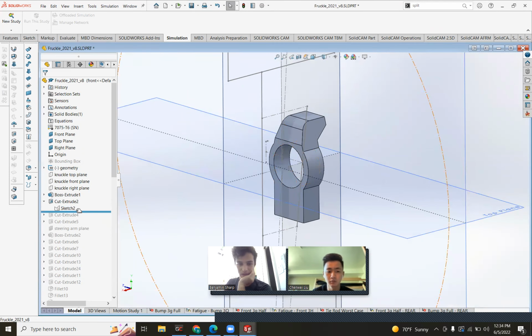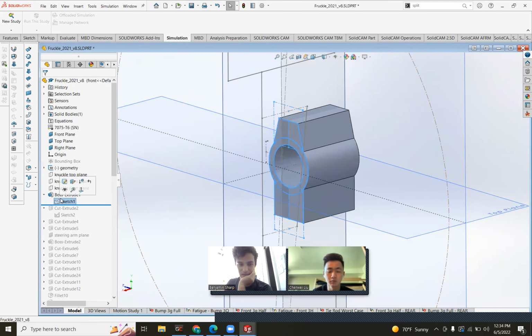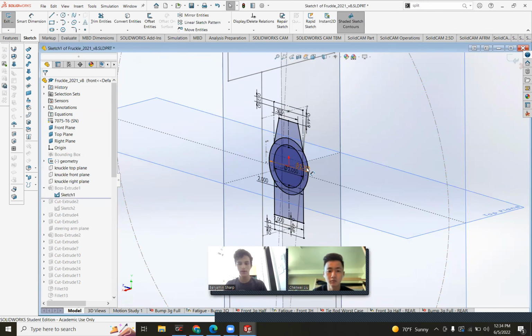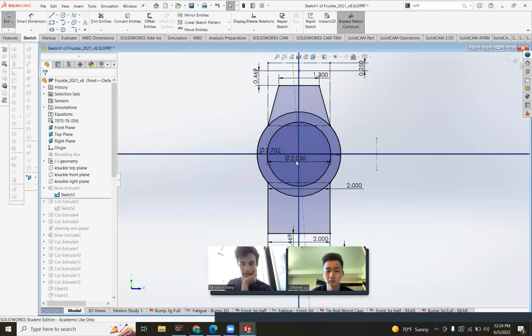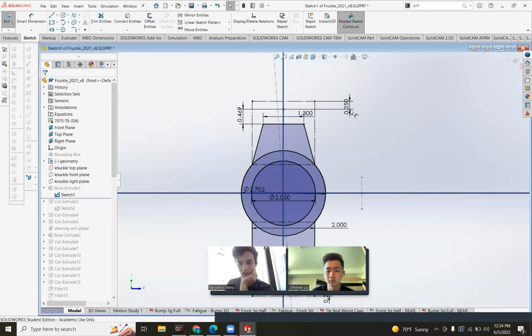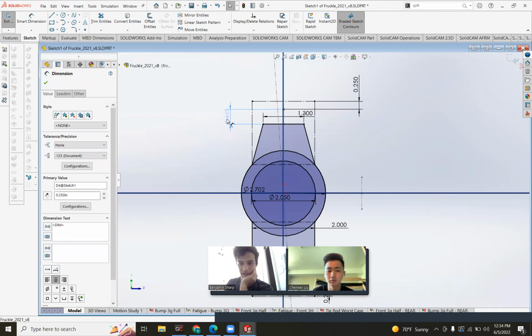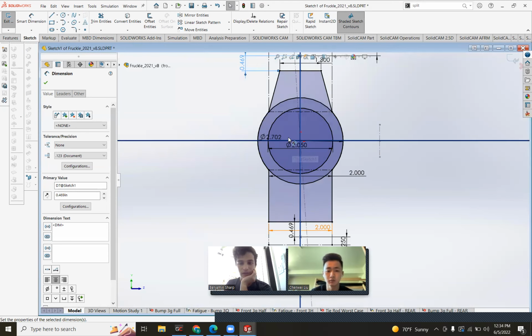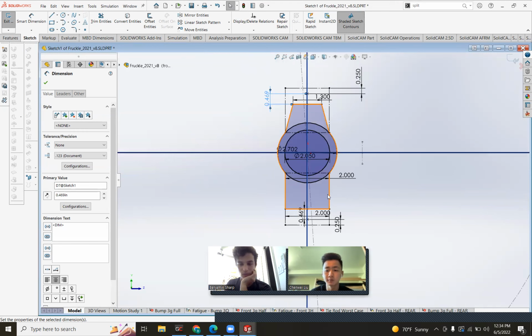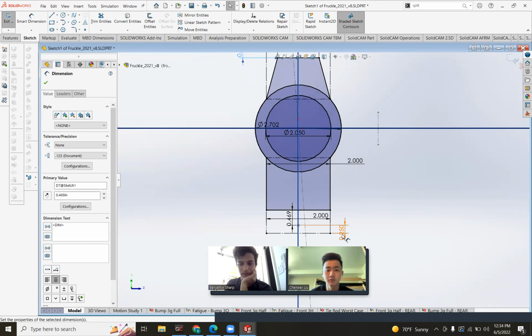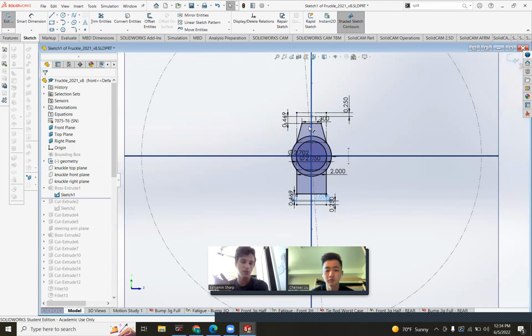And these dimensions here are based on the sketch with dimensioned offsets. So you have a quarter inch of clearance for the spherical bearing, and then you have some more clearance for the bottom of the bearing and a spacer. These values are set from the center of the wheel bearing. Same thing on the bottom with the center of the spherical bearing and a spacer right here. And then the widths, you can choose what you want.